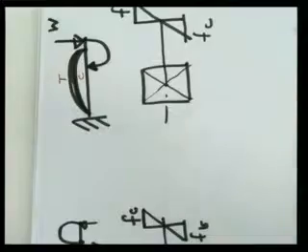So you have to note which type of beam it is. If it is a cantilever beam, then the top layer will be subjected to tension and the bottom layer will be subjected to compression. But if it is a simply supported beam, then the top layer will be subjected to compression and the bottom layer will be subjected to tension. That is why I am taking the second problem as a cantilever beam, right? So now you can read the problem, what the problem is given.